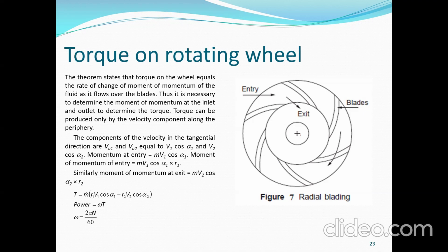So, pag dito ng entry mo, palabas sa pump yun. Okay, double check. So, power is torque times omega, omega is 2 pi N over 60. So, makukompute mo na yung power. Sa pump to, sa turbine, yung sa blades, didivide mo pa siya ng mga hydraulic efficiency, kung ano pang mga efficiency, lalabas na yung motor.